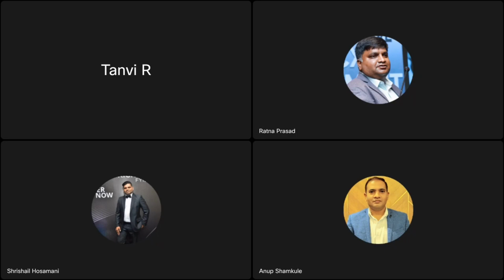See, actually, there is one more query. We can control meshing using tools like slicing and body splitting, and also how closely do the simulation results in Creo compare with those from Ansys? See, when you're looking at splitting, body splitting and slicing, these are mostly related to the body controls when we are doing the meshing.